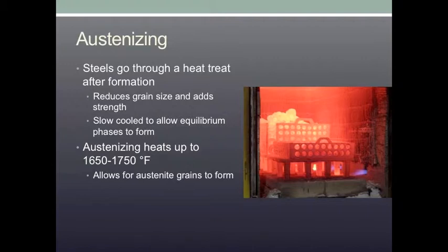By heating up the steel, the austenite phase is allowed to form. This is usually done in a range of temperatures from 900 degrees Celsius to 950 degrees Celsius. By heating the steel at temperatures larger than 950 degrees Celsius, the steel can become superheated, which is a problem because when quenching, this can lead to quench cracking because the temperature difference between the steel and the water is so great.